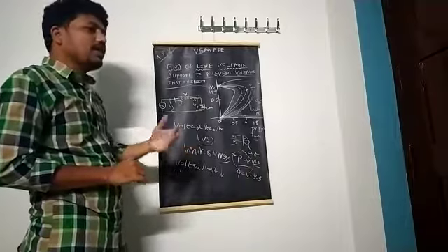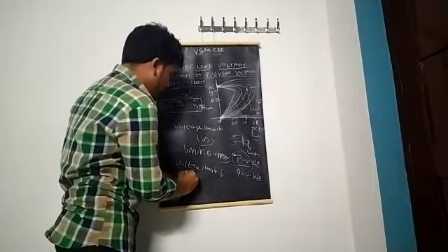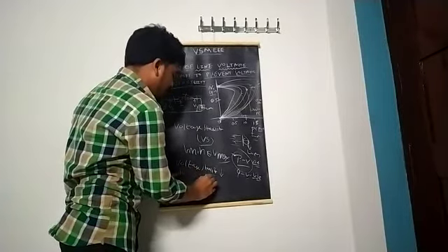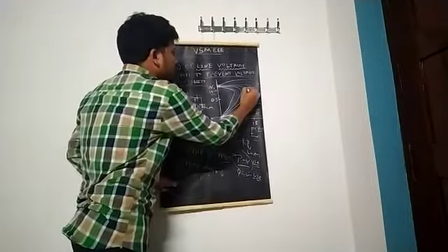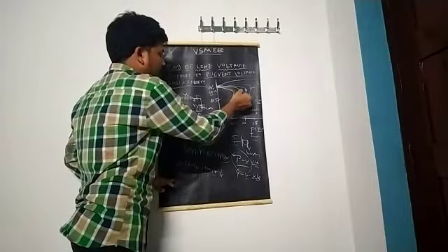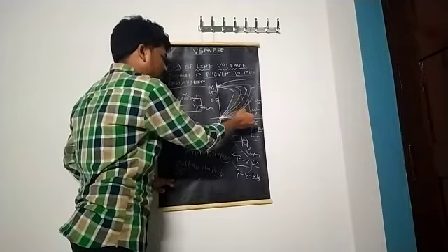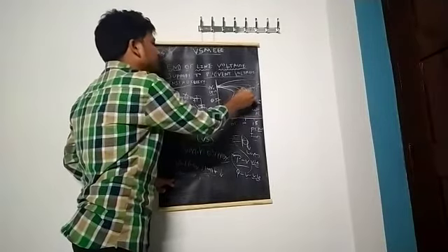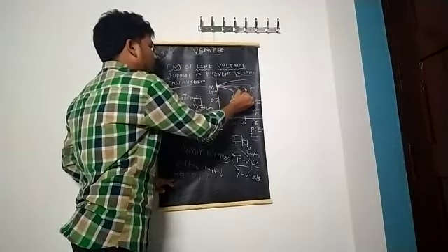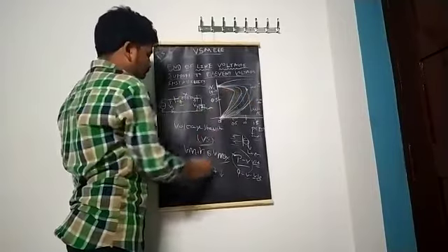Generally, the inductive loads and capacitive loads mean lagging loads and leading loads. Voltage stability decreases with lagging loads. Here you can observe this is the unity power factor, this much voltage, and this is the lagging power factor, with some lagging factor. For example, 0.85, 0.9 lagging, and 1 is unity. Voltage from unity to 0.95 lagging, and from 0.95 to 0.85 lagging, the voltage stability will decrease.